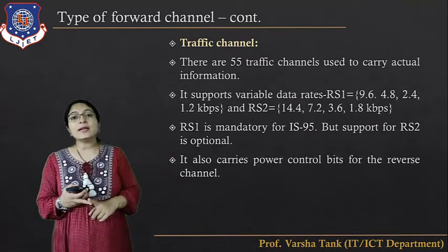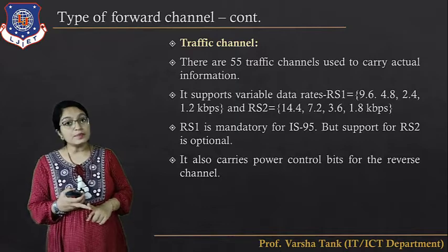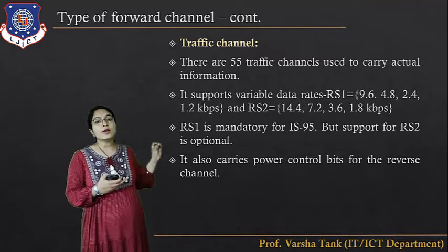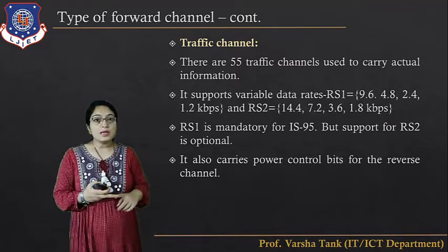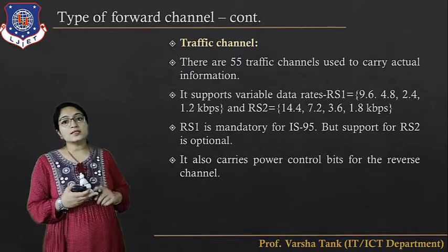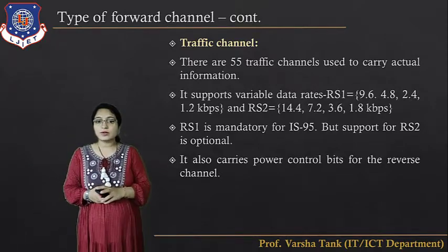RS1 is mandatory for Interim Standard 95 for the CDMA, but support for RS2 is optional. So if you are using the Interim Standard 95 CDMA, then it is mandatory that you have to use RS1. It also carries the power control bits for the reverse channel.